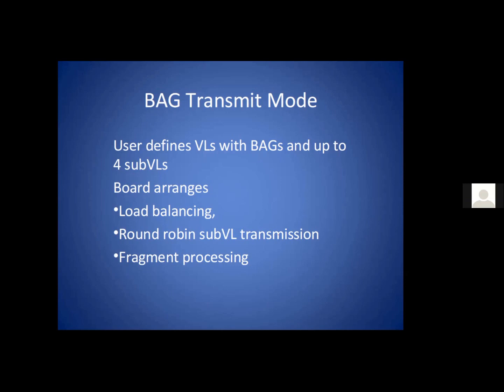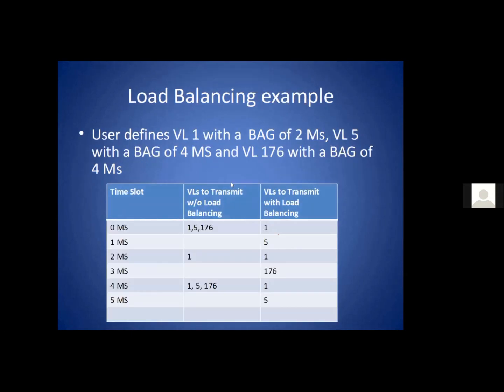It has to follow the rules that I gave you. These are the bags, these are the VLs, these are the sizes. But having given you the rules, the actual order sequence, that's up to the board. The board arranges the load balancing and round robin transmission and fragment processing. We'll get to what those things are. And so we take all of that timing issues off of the user's back.